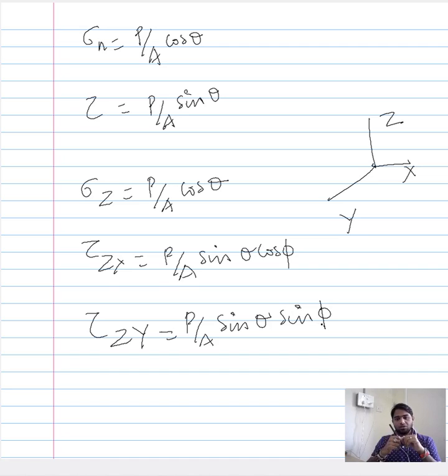In 3 dimensions, theta is the angle between the loading direction and the normal to our region of interest, and phi is the angle between the plane that comprises the loading direction and the normal to the x axis. By having these 2 angular dimensions, theta and phi, one can describe the mechanical condition experienced by any plane and any direction in a 3-dimensional setup.